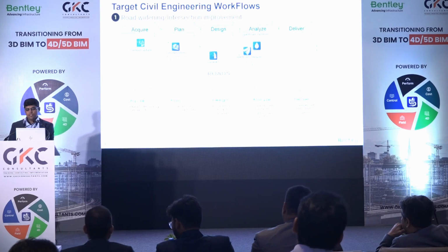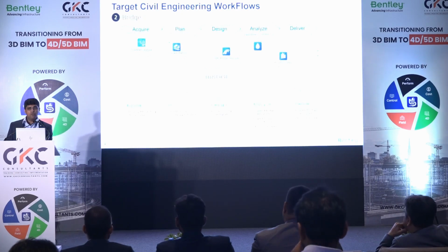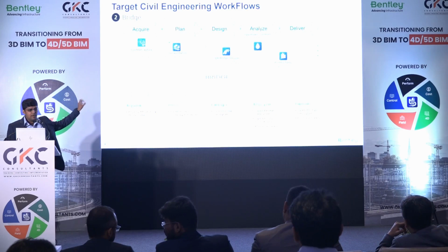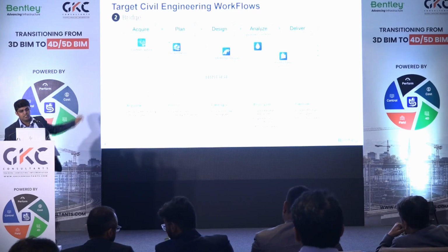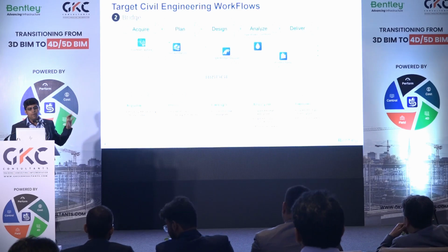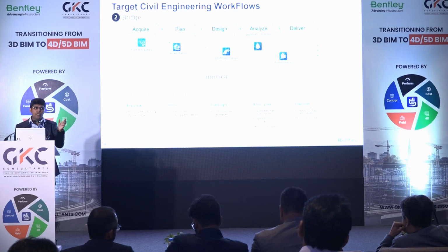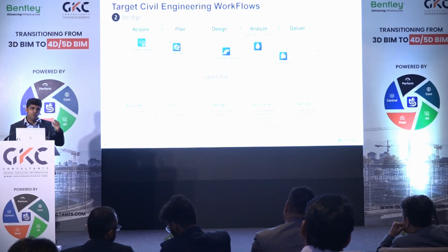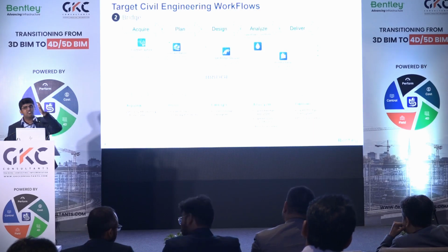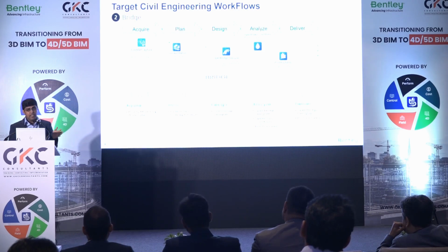Similarly, we have a workflow built with all those 9 product lines for bridges as well. The only thing is the first 2 stages are one and the same. The third stage is OpenBridge Designer, where you carry out the detailed design of your bridges. You bring your road alignment from OpenRoads or OpenRoads Conceptstation, and take it to bridges. At the exact chainages, you can build a 3D model of a bridge, and you can take the same model internally for analysis and design.